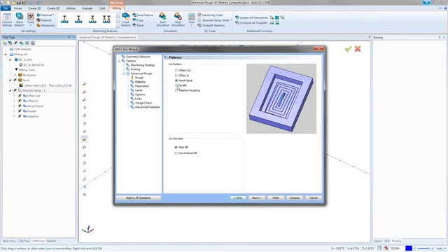Then we have one for parallel. I usually don't use this on a part like what I have on the screen here. I'd usually try and use this for something longer, especially if I've got some long tubular kind of shape that's going down the middle of a part. I'd like to have this rough those things out. Really, I use the parallel anytime I'm looking for a longer cut. So I want something longer, and the parallel is going to get it.